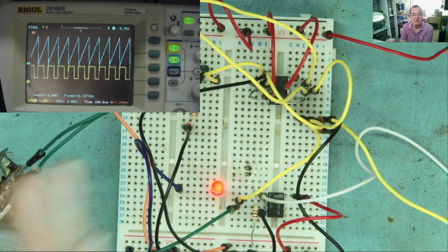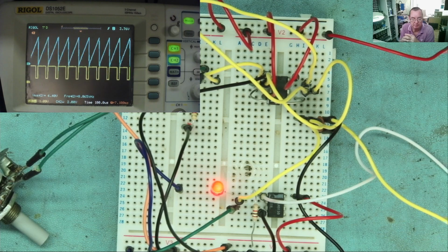The pulse width modulator, the oscillator type thing, the controller, usually on its own right will not fail. Sometimes the circuits it requires to supply power to start up may fail, so it doesn't get any power to start off with, therefore it can't run. But all in all themselves, they're reliable. You can have faulty timing components, the capacitor, the resistor that sets the frequency, but again, that's not generally doing too much work and they usually don't fail.